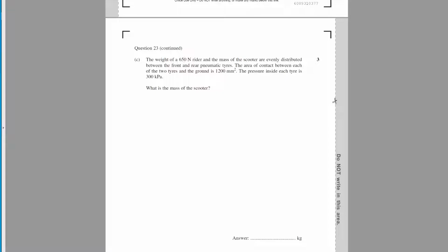We know stress equals force over area, so force equals stress times area. We want to use megapascals and millimeters squared together. Because I don't like converting anything squared, I find it difficult and problematic, I'm going to instead convert this to megapascals.